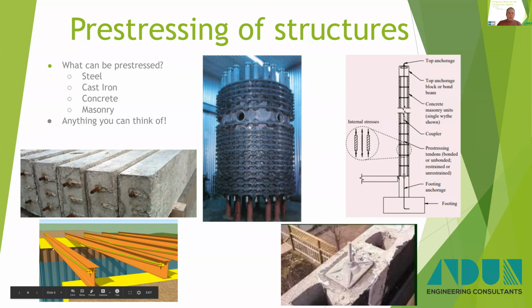You can even pre-stress, or pre-tension, steel. Not very common, but it can be done. And again, it's normally done to increase the economy of a structure. Because we use higher grades of steel to form the pre-stressing component, it's lighter than the equivalent non-pre-stressed material, which gives us an advantage when it comes to weight and the economy of a structure. But that can often be offset by the complexities.